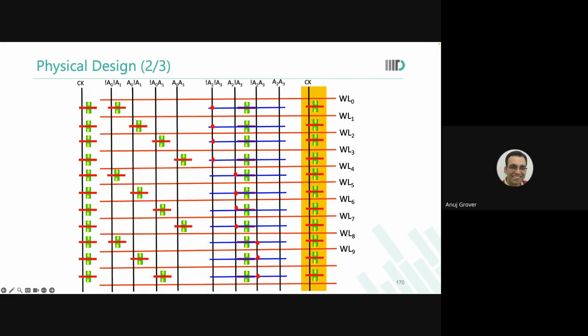But this also, when we divide it into cells, is a constraint on the number of rows we can increase at a time. Yes. So now you remember why I brought your attention to the step size when we were talking of a compiler datasheet. Go back to that compiler datasheet and see that the step size is not 1 when it comes to rows. It's always 2 or 4 or whatever the multiple is. It tells you the minimum step size that you will have in terms of rows. It has to be defined in the compiler datasheet.